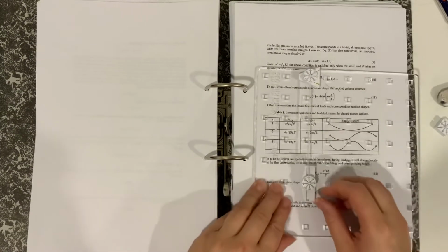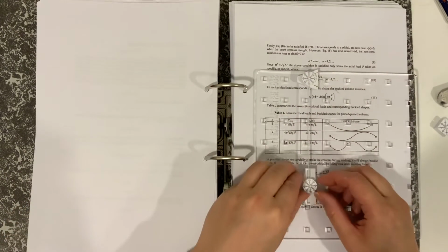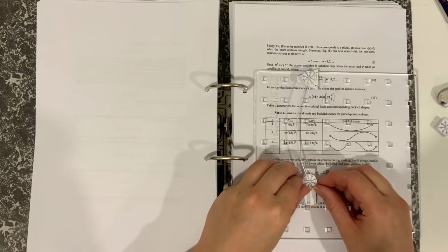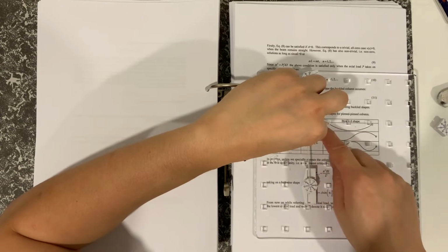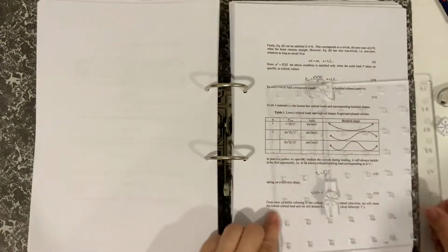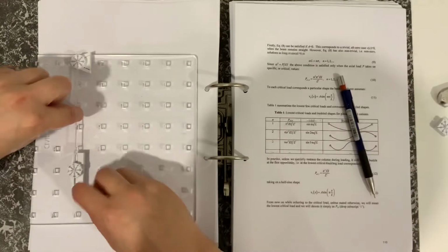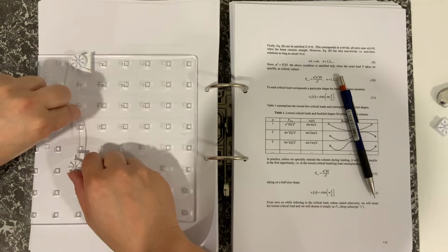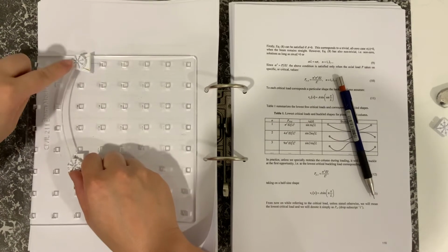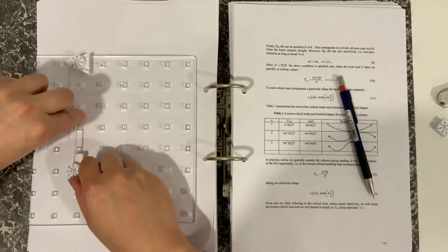So here we stick this on here, and we can see that it buckles into 1/2 sine wave. Now, what happens if that was a column, so this is a column, and this is maybe a beam coming into the column providing some lateral restraint, which I'll show by pushing it, and we can see that it buckles into 2/2 sine waves. So it would tend to buckle into the lowest mode, which would be the 1, but if there was something there, then we do have enough for a solution.